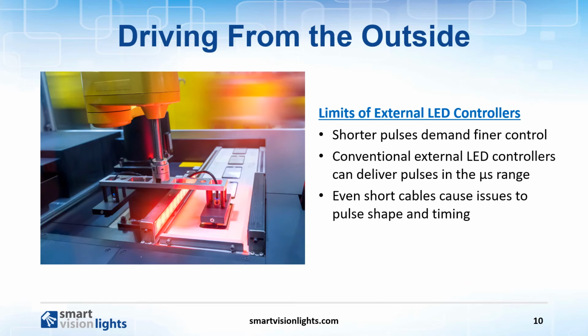Measured in intensity over time, an LED pulse should exhibit a square shape, which indicates that the die is achieving full output power more quickly. This ensures that the LED is not still rolling on when the camera shutter opens, but is illuminating the target with its full intensity. Otherwise, pixel blur can begin to creep in.